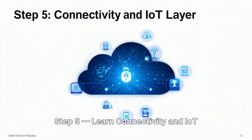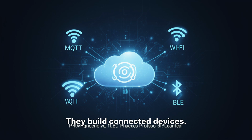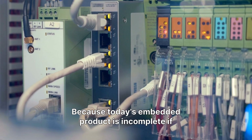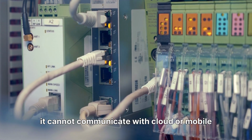Step 5. Learn connectivity and IoT layer. Modern embedded engineers are not just firmware writers, they build connected devices. So learn MQTT, HTTP, BLE, Wi-Fi, device provisioning, OTA firmware updates. Because today's embedded product is incomplete if it cannot communicate with cloud or mobile apps.